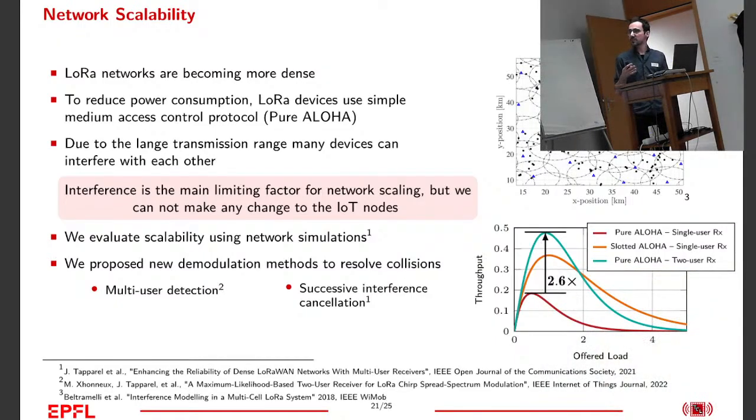So for us, we've evaluated how much of a problem collisions are. The difference, for example, between Wi-Fi and LoRa is that, as it has a long range, you have a lot of devices that interfere with yourself. Unlike your Wi-Fi, where the neighbor two houses further will not hear it anymore. So that quickly creates a lot of collisions within the network.